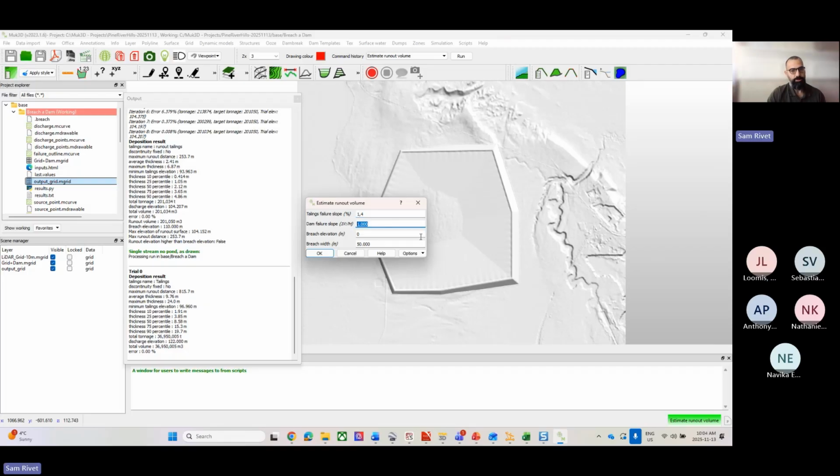And then in terms of the slope, so how that breach is going to look through the facility, how that trapezoidal channel will be defined through the facility, I'll say 6 to 1. Breach elevation, once again, I'm at a range. So this goes up to 125. So I want to see it for 105 and 110. And my breach width, single value, I'll keep it at 50.